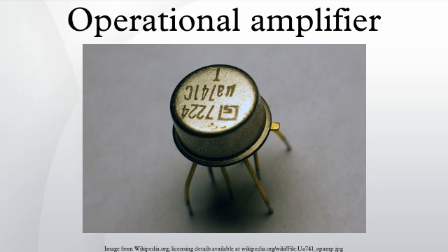Voltage amplifier: a current signal i at Q15's base gives rise to a current in Q19 of order i HFE squared. This current signal develops a voltage at the bases of output transistors Q14/Q20 proportional to the h_ie of the respective transistor. Output amplifier: output transistors Q14 and Q20 are each configured as an emitter follower, so no voltage gain occurs there. Instead, this stage provides current gain, equal to the HFE of Q14.